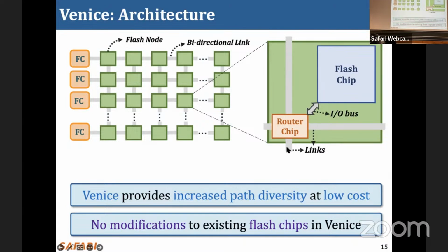Even though the die is small, when you want to package it, you need to spend a lot of time. So we went through all the different standards related to the distance between I/O pins, like the I/O pads, how big they should be, depending on the frequency and the resistance of the wire. Of course, it's not possible to be very accurate, but we did our best.